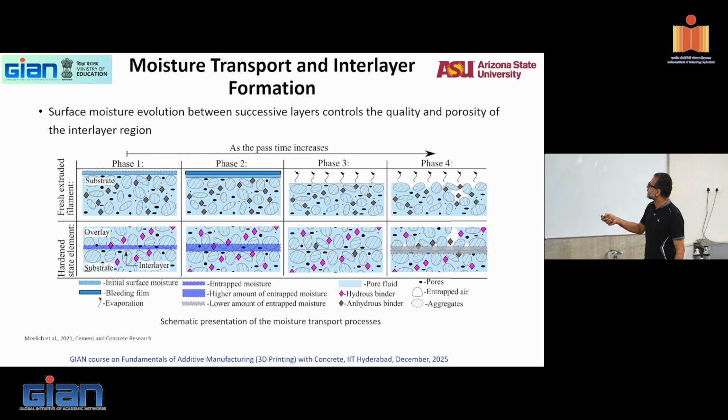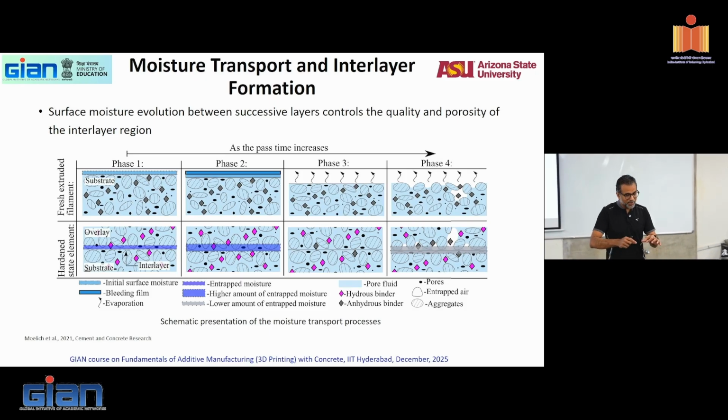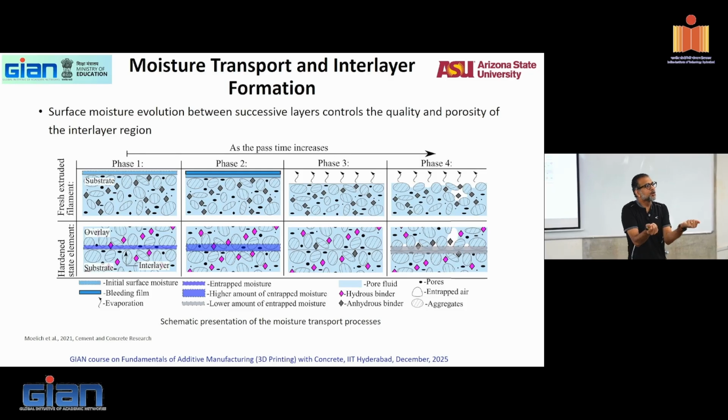So this is with time, right? Simply, you're talking about time and seeing how the water is evaporating. This is your regular cement, regular concrete itself. Your regular evaporation from your regular concrete, right? Now, what happens with evaporation from regular concrete is it's evaporating from a bulk. What happens now? It's evaporating from a thinner layer, right? So what happens? You now have suction pressure from water capillarily rising from the top.